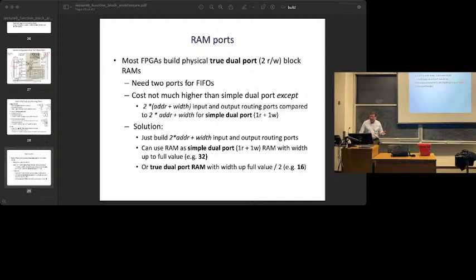But another thing that you could do is we could try to reuse the RAMs that are our LUTs. A lookup table is a ROM, right? It is a read-only memory. And a 6-LUT, it's not a huge memory, but it's actually significantly bigger than a 4-LUT. So with 4-LUTs, it was kind of tempting. Could we maybe reuse those lookup tables as RAM? And when you went to 6-LUTs, it actually got more tempting still because it's just bigger, right? There's more memory in there.